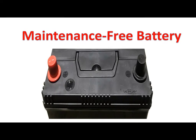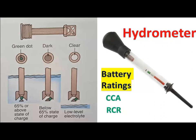Most maintenance-free batteries have a built-in hydrometer in the top of the battery to indicate battery state of charge. If this hydrometer indicates a green dot, the battery is sufficiently charged for test purposes. When the hydrometer appears dark, the battery charge is below 65%, and a clear hydrometer indicates a low electrolyte level.